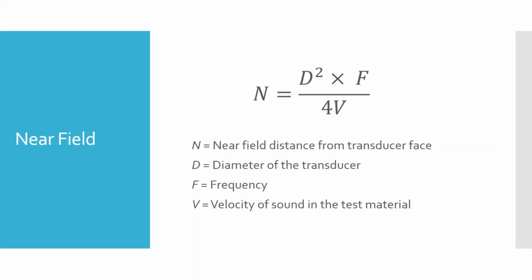So if I hold up these two probes, I've got in my left hand the probe for composites, that is a 1-inch diameter. And in my right hand, I have a probe designed mainly for metals. I can't remember, 0.37 inch diameter. So of these two, which one is going to have the deeper near field? Which one is going to be worse at detecting surface flaws? You see Nick pointing to my left hand. You're right, my left, that's the big one. That's the one designed for composite.